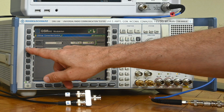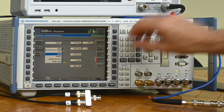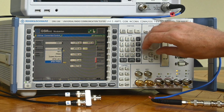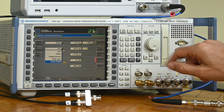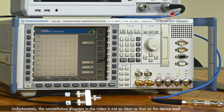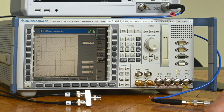That is actually because it is not yet set to the 8 phase key shifting mode. In order to do that, we go away from standard GMSK to 8 phase key shifting here. And now I should, yeah, I get to see it. I get to see a constellation diagram. It's measuring its own signal, 8 PSK.